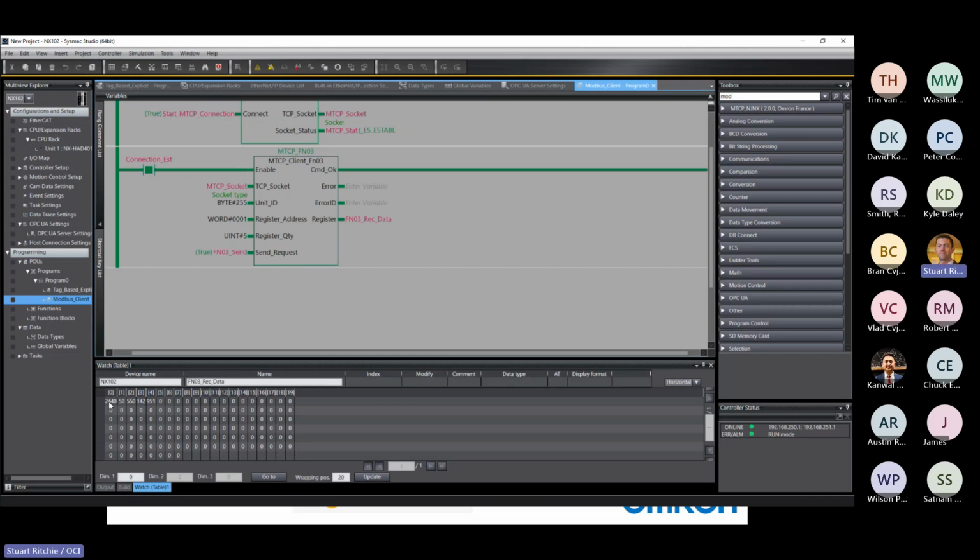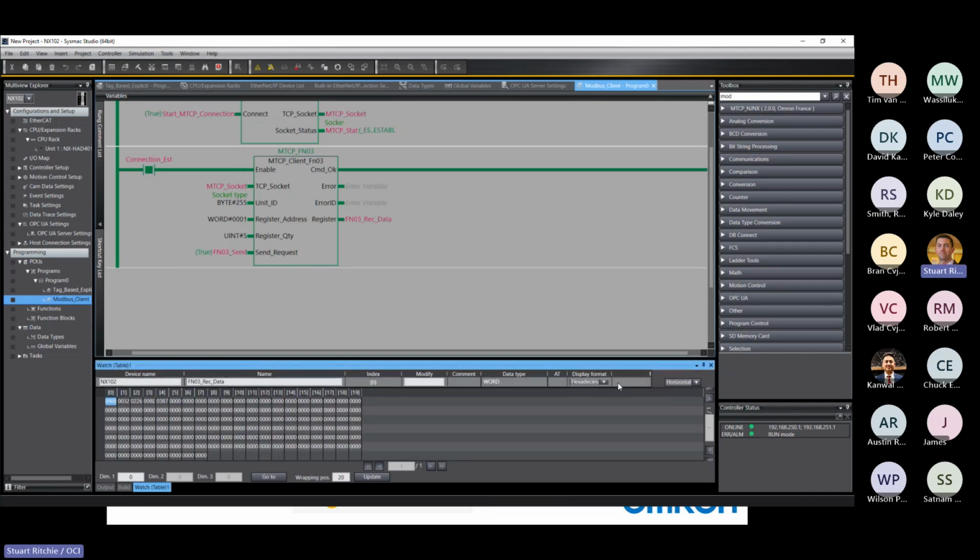And there you can see the first 5, and we'll change the view from hex to decimal. So 2440, there's a divide by setup on this one. So that's actually 24.4 volts. That's telling me the output voltage is, and that's outlined in the manual. I'm just going to turn that potentiometer down a notch on the power supply just so we can get some new data in that parameter.